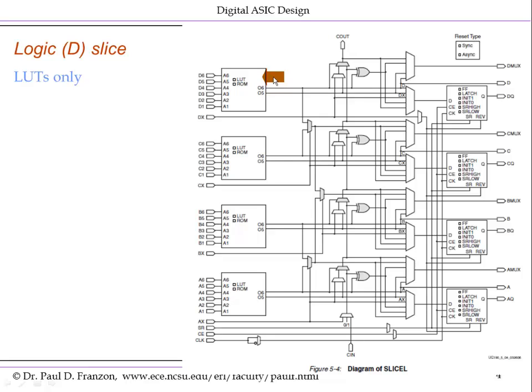There's still SRAMs. The lookup tables are still programmed by having logic not shown here, writing bits into an SRAM to implement a particular lookup table function. However, you as the designer cannot use them as SRAMs. You can only use them as read-only memories or lookup tables. Everything else here stays the same in terms of the steering logic, the carry chain support, and the 4 output 1-bit storage elements.